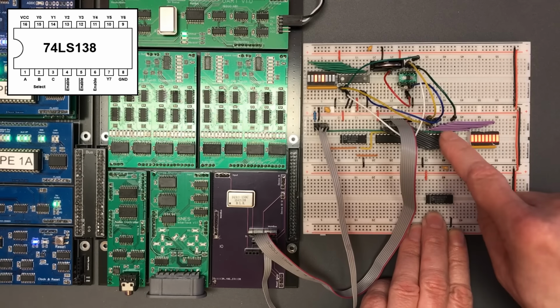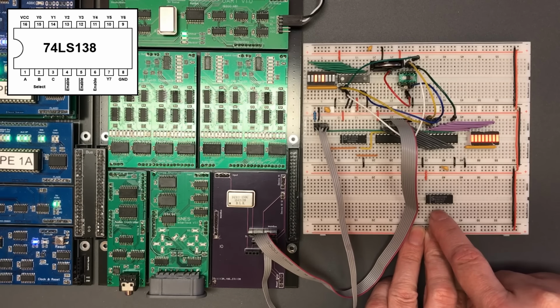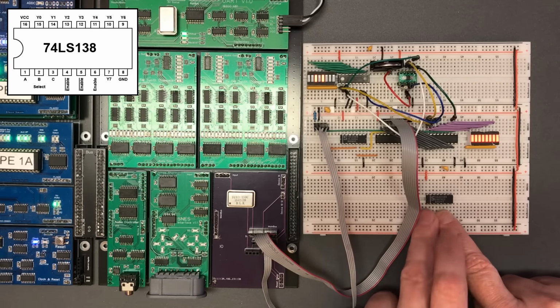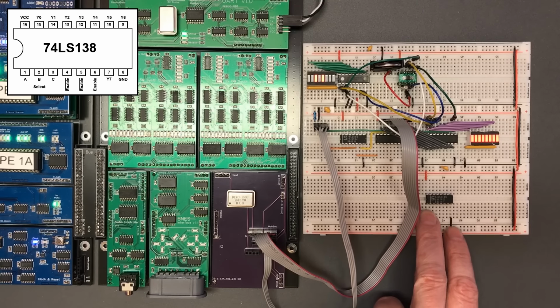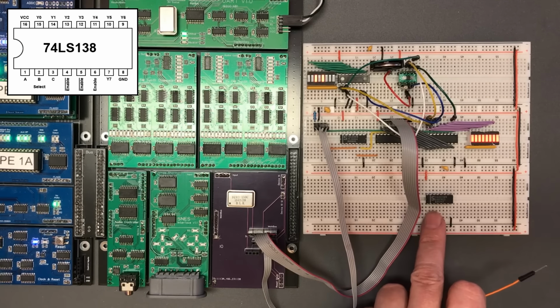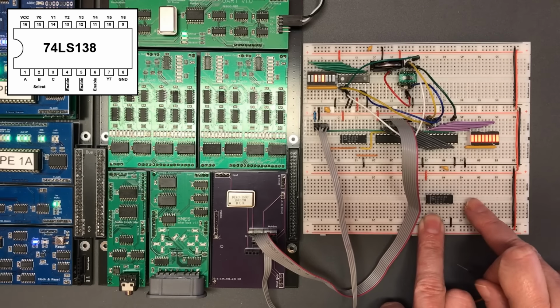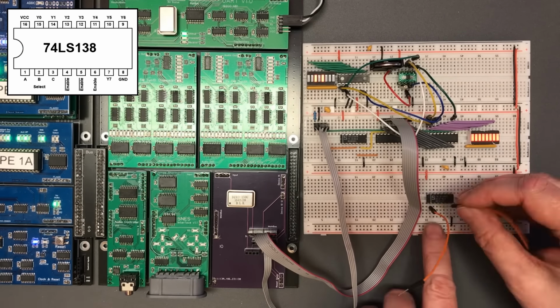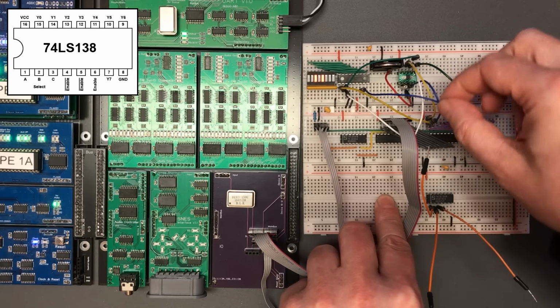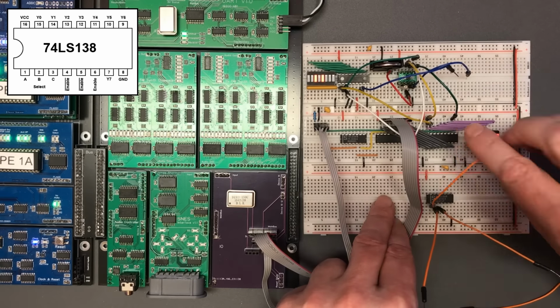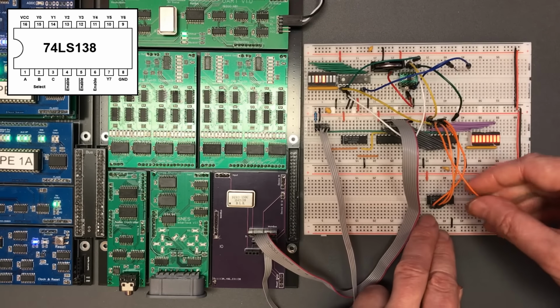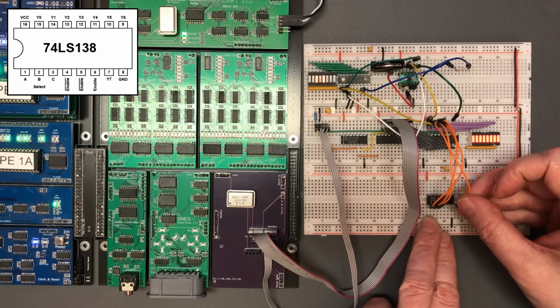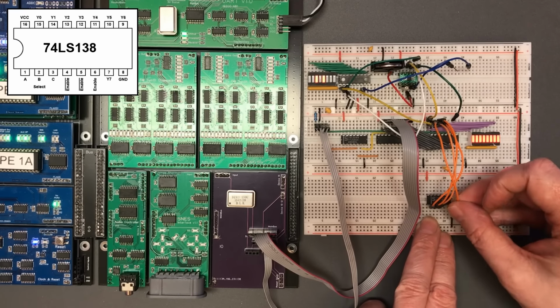So I'm actually going to pretend we've got 4 bits of address and use one of the enable lines to provide that extra. So with just the one of these chips, we have indices 0 through 7 produce no output, but 8 through 15 will produce 8 usable active low enables. So let's take out those chip select lines. And then that top bit goes into the active high enable, which is that one.